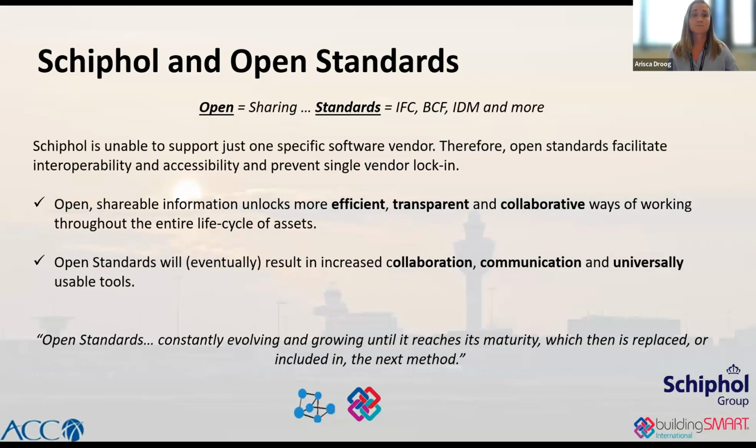Next slide. So for interoperability, to avoid risks and to ensure a future-proof and long-term solution, Schiphol Airport cannot support just one specific software vendor. So the focus is, apart from the native files, also the openBIM standards like IFC, BCF, IDS, and others. As an organization, we understand that open standards and open shareable information unlock more efficient, transparent, and collaborative ways of working throughout the entire life cycle of assets.